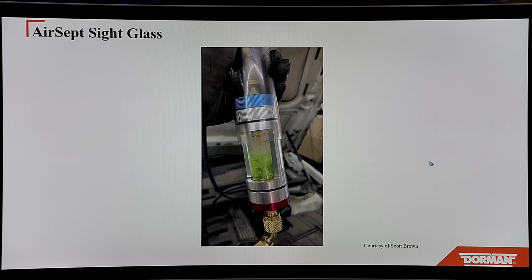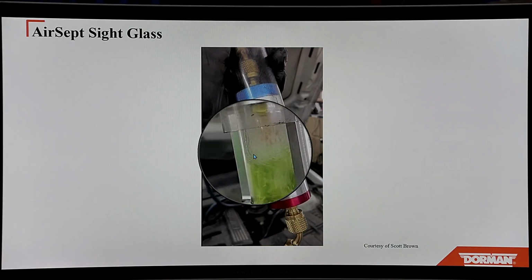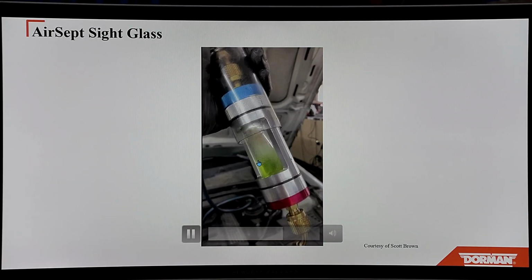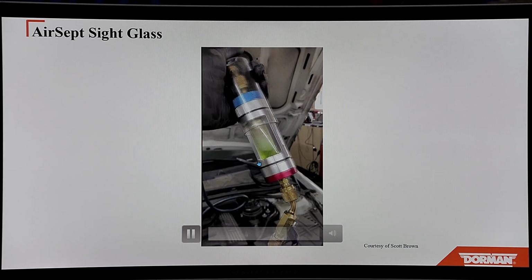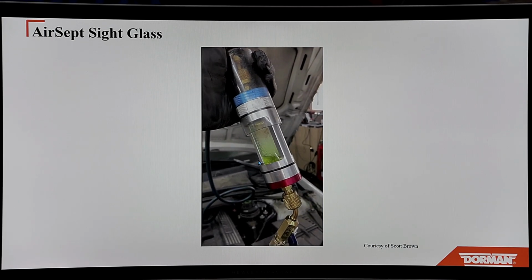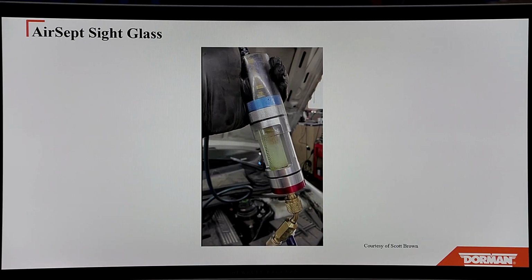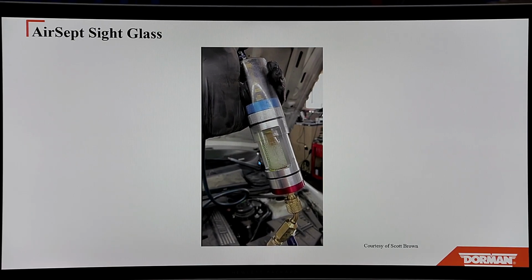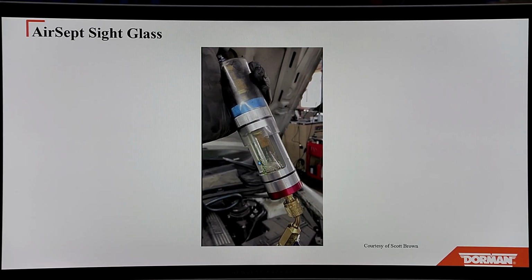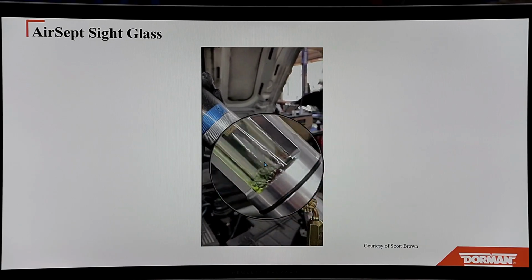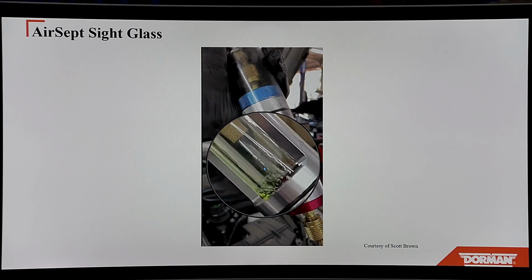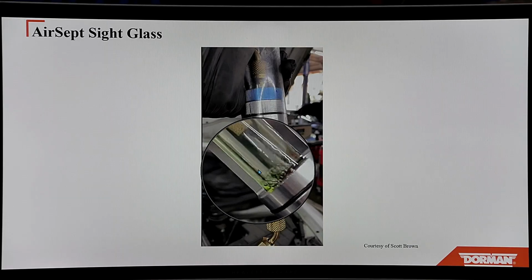When you open the low side up, you see how this is starting to boil off? You know what that's telling me? It's telling me that the high side discharge is putting refrigerant out. The low side is actually able to suck it in. That way you know if your compressor is working or not. And then you could look for oil debris, and if it's dirty and black or there's a lot of dye or a lot of oil.